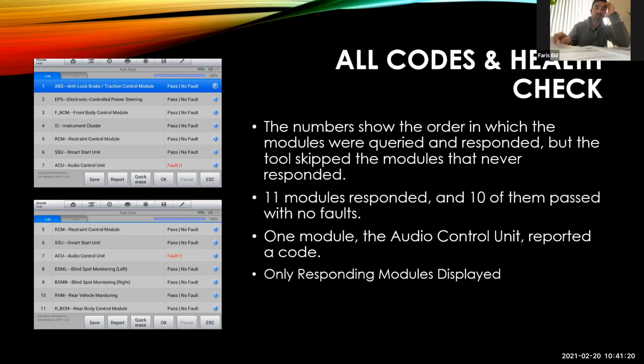So would you still have a fault code, even if you can't talk to that module? Yeah, you'd have a fault code probably from other modules that can't talk to it, we'd hope. Not always, but we'd hope. How about if it just doesn't talk to it because the software in the aftermarket scan tool didn't have the ability, or there's nothing wrong with the module, it just couldn't talk to it?